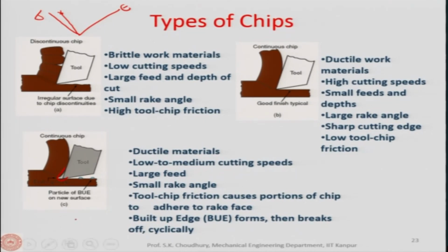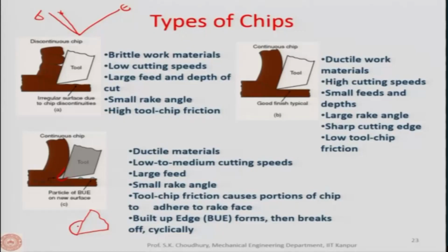And what happens is that it remains on the tool because of this reason. So let us say this is the tool, and here I will exaggerate, this is the piled up built up edge. You can all see this, right. Now, the built up edge is a very hard material, because it is strain hardened material. The chip is strain hardened because of the plastic deformation, so this very hard material is getting piled up in front of the tool.